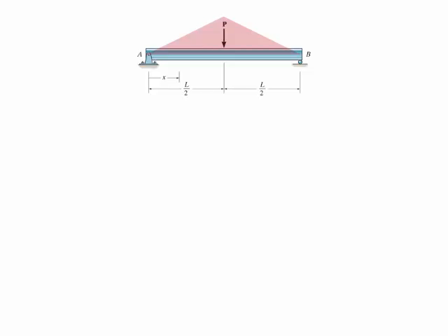How do we use this method? Well, we need to set up an equation that describes the bending moment along any point on the beam, and for that we need to draw the free body diagram of all the applied forces as well as the external reaction forces, and that's what we have here. So we calculated the reaction forces at the supports. They are equal in magnitude, and their values are the load P divided by 2.